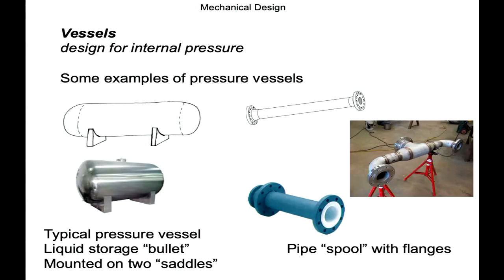Have another look at this one. This saddle point, what's nice about it, it's providing a nice, extensive region of contact, reducing the contact or Hertzian stresses around that vessel. However, if you think about that vessel, it is essentially a uniformly distributed load with two reaction points, one there and one there. So, it's going to want to bend in the middle, like a beam would bend. It just so happens that this beam has a hollow circular section.